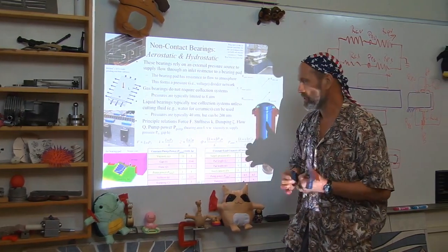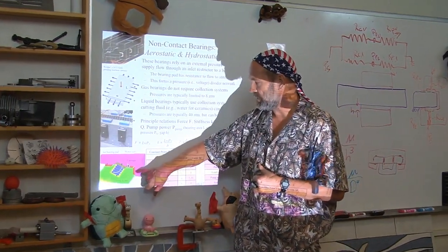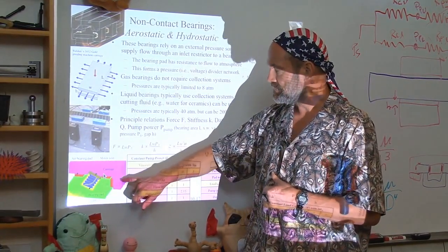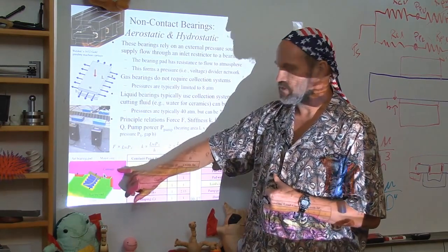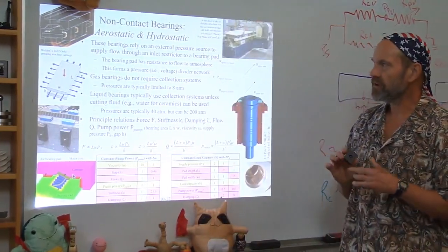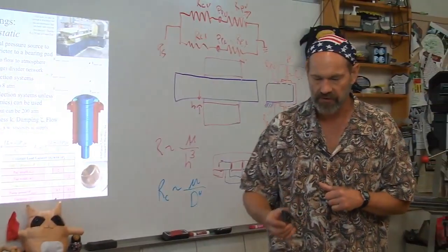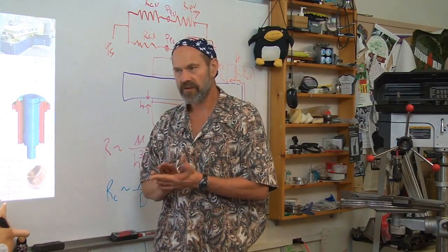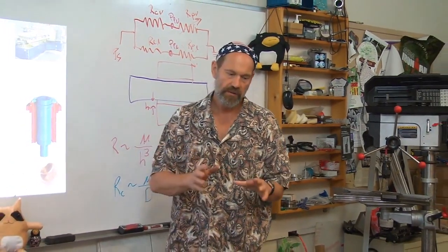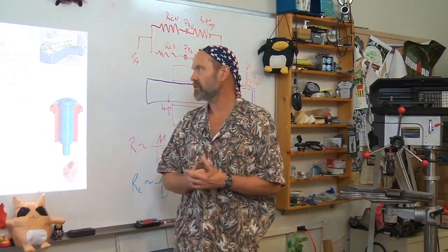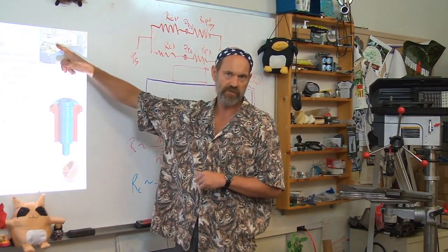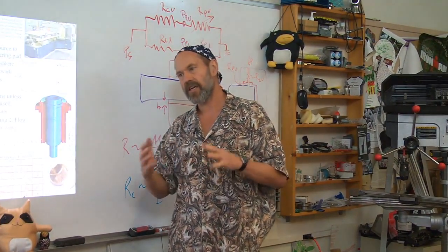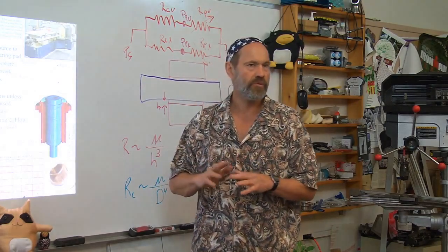Or for very, very precise systems, you can then pump epoxy behind them and fix them in place permanently until you break the epoxy, without having to precision machine your carriage. So some very interesting novel ways have been discovered for making very, very high precision machines using very, very simple structural elements, air bearings. You can also use this method with hydrostatic bearings. That's actually how we do these big ceramic water bearing grinders. And achieve very, very high load capacity, high stiffness, and a virtual immunity to dirt.